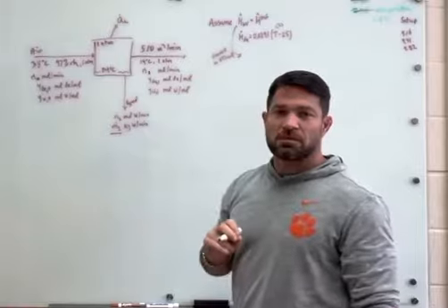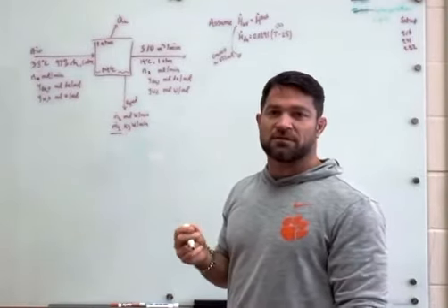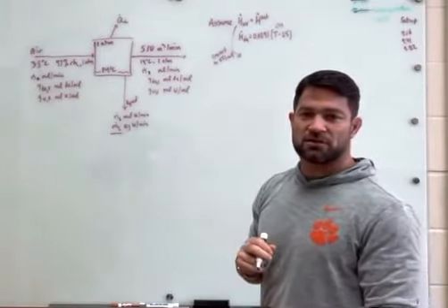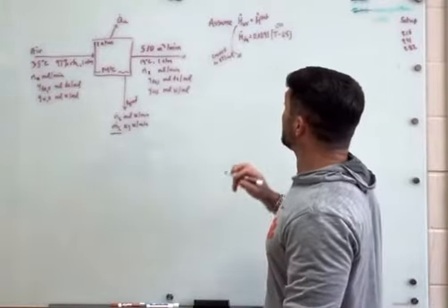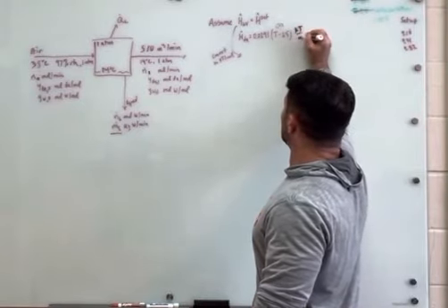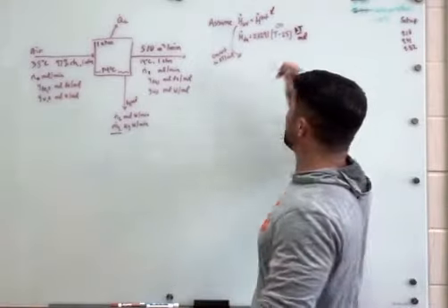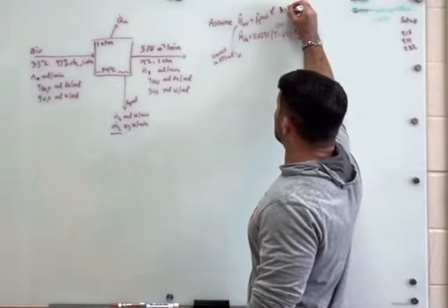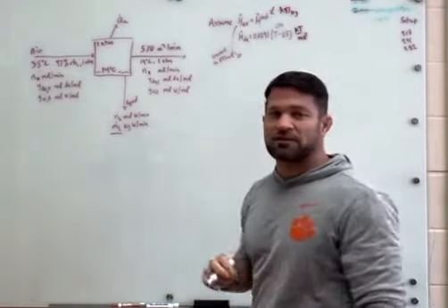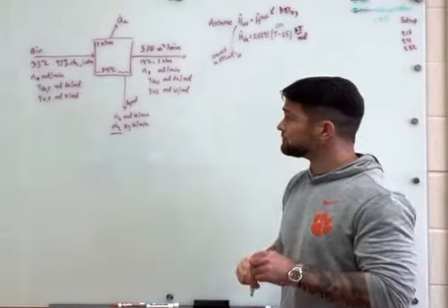We're also going to assume, according to the problem statement, that the enthalpy of the water vapor is that of the saturated vapor at the given temperature. It also gives us a relationship for the enthalpy of dry air: 0.0291 times (T minus 25), in kilojoules per mole. The saturated enthalpy values for water from the steam tables in the back of the book are in kilojoules per kilogram, so we're going to need to convert them to moles, because I'm going to solve this problem in terms of moles.